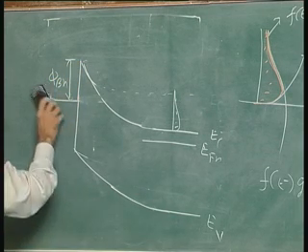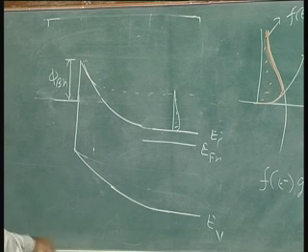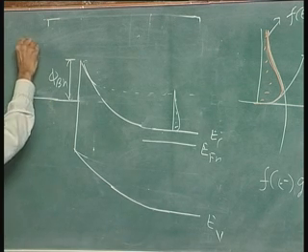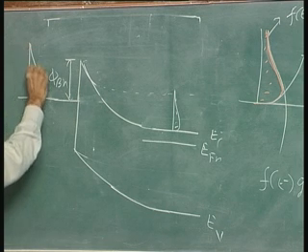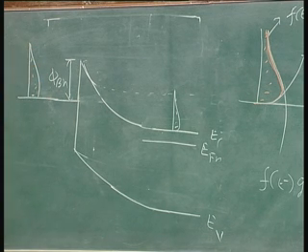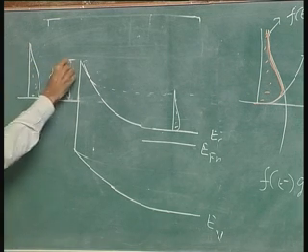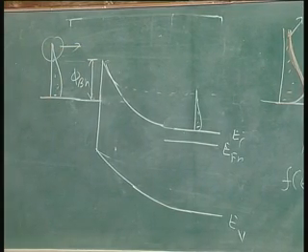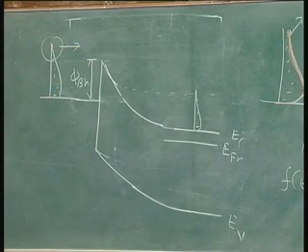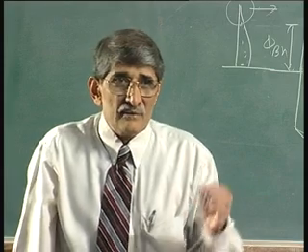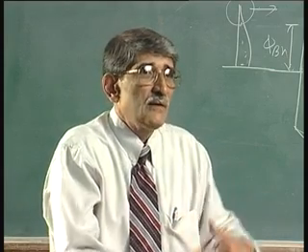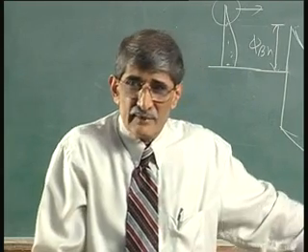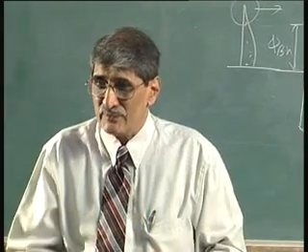Okay. So, as far as the distribution of electrons is concerned, here what has happened? We have drawn it earlier like that, a thermal equilibrium situation. Whatever electrons are there, they can still cross the barrier, because that barrier has not changed. Whatever was giving rise to the current, electron transfer from the left-hand side metal to the semiconductor, remains the same thing, that we called I naught.